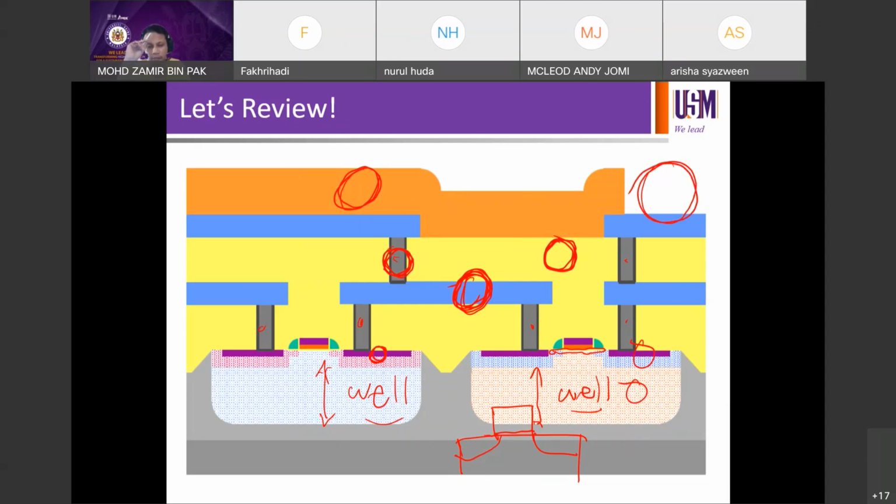Good, bond pad. Okay, now you look here, you see up to metal 2, right? Now at least it's not that bad, it's not that obvious, but you can see that your switching process is down below. Maybe it doesn't look too obvious now because it's only up to metal 2. If we talk about metal 3, then you have metal 3, then metal 4, then metal 5, metal 6, metal 7, top metal.